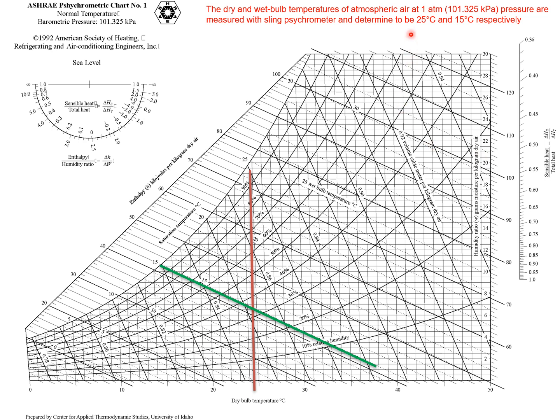Based on these two parameters, you will find an intersection point here. This intersection point is very important because based on it, we will find the other parameters that we want. The first parameter that we are looking for is the specific humidity. The specific humidity is given here. So this is the specific humidity.